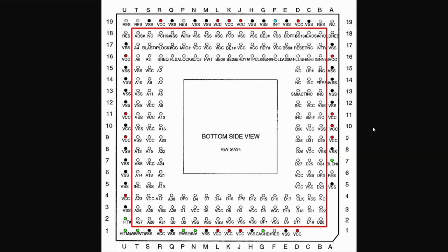Okay, I'm sorry, I have one additional mod to show you. This is the pinout of the Pentium Overdrive. Everything within the red square is the old 486 pins. The others are the additional ones that are used only by the Pentium Overdrive. And down here is a write back, write through pin. The 486 has a similar pin, but it is in a different position. If you pull this pin down, then the internal cache is forced to write through. You can very easily do this by placing a 1K resistor between these two pins. As simple as that.